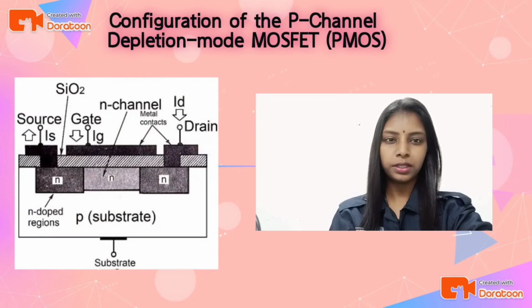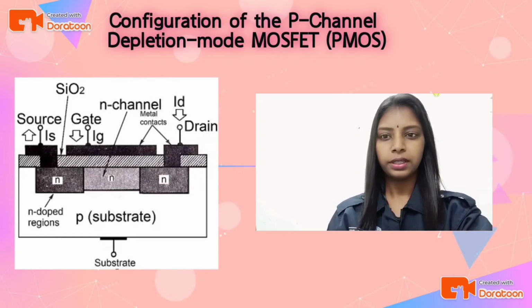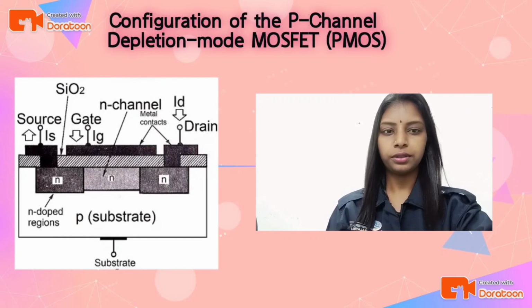Configuration of the P-channel depletion mode MOSFET. The previous analysis applies in principle also to the P-channel MOSFET. The construction of the P-channel depletion mode MOSFET is the reverse, as shown in the figure beside: an N-type substrate and a P-type channel. The terminals keep the same names, with reversed voltage polarities and current directions. In a P-channel device, ID flows from source to drain, entering the source terminal and exiting the drain terminal.